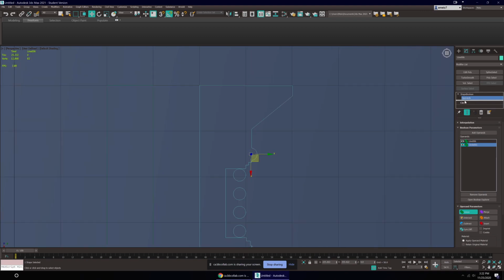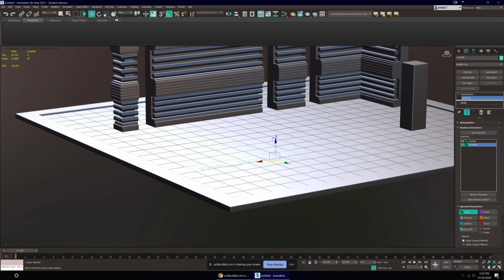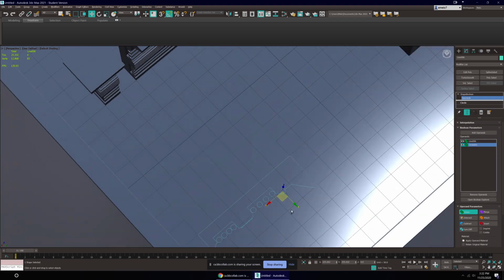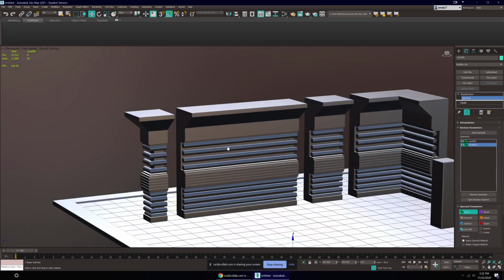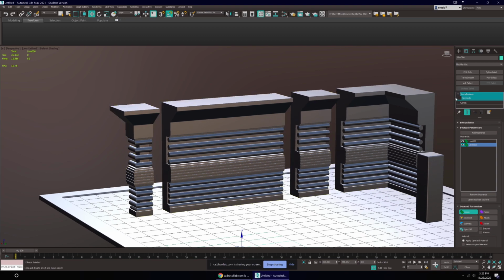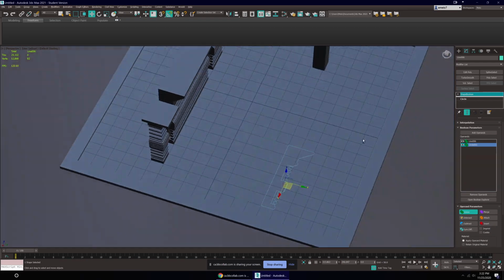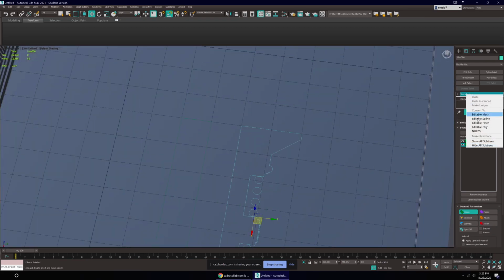And you see this little bar here? This bar means that this is independent than what's actually being looked at here. And that's why when I move this here, nothing's actually updating here. But if I move this down below this line, I might actually not be able to do that. Yeah, you know what? Booleans are not able to be instanced. So I would have to collapse it and readjust it. So I'd have to do this,